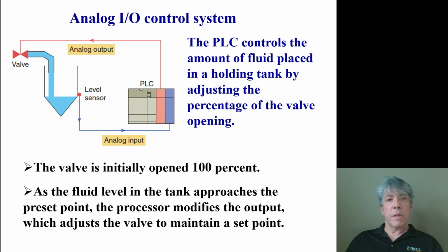You just need to be aware that there are continuous signals and how they get into the PLC and out through analog to digital conversion in, digital to analog conversion out. And you need to know that probably the most bulletproof method of communication for these analog signals is 4 to 20 milliamp signals. That's what you'll see very commonly at any chemical manufacturing plant or any of these places that use continuous signals.